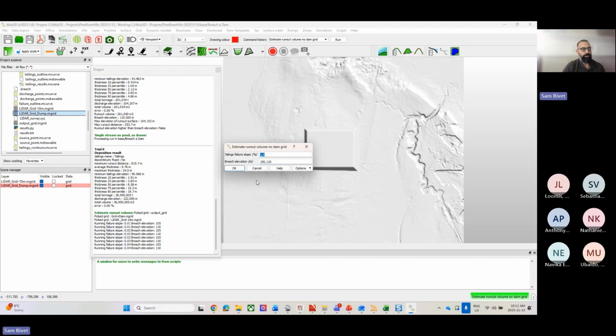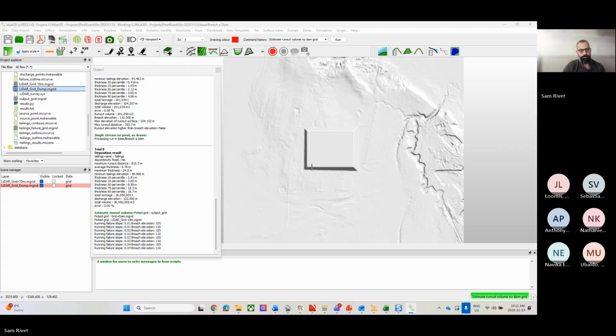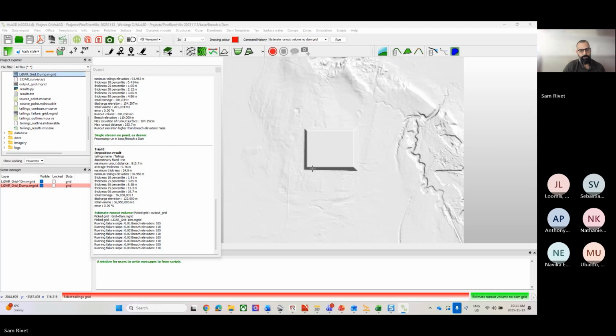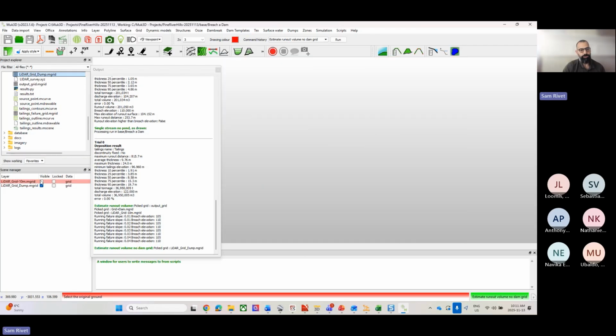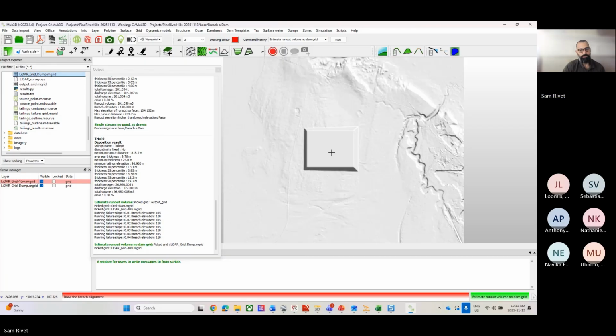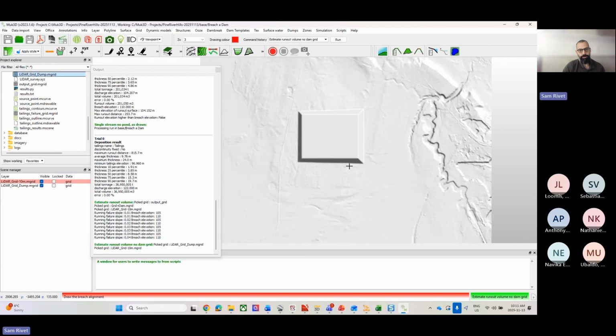So I'm going to do multiple failure slopes and multiple breach elevations. Run all those scenarios. It's asking me to select the tailings grid. So that's just going to be my grid with the dump merged in. Just isolate it and make sure it's selected, that one. Layer drawn around surface. And then just quickly draw my breach alignment. I'll draw it over here.